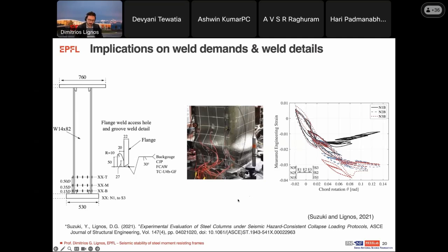So that by itself means that we could consider simplifying some of the weld details in the fabrication process without having to use very expensive welds, which in this case would be complete joint penetration welds. Plus the fabrication detailing could be a bit simpler, which is, I guess, good news if you're looking into pushing steel construction in projects related to the construction of new buildings.